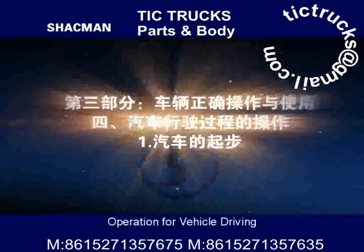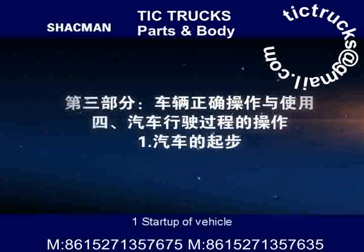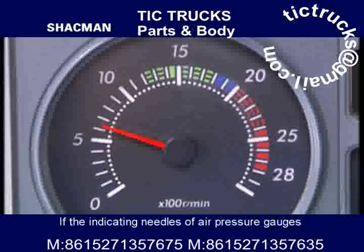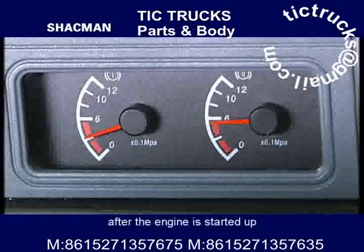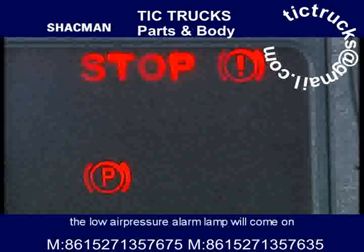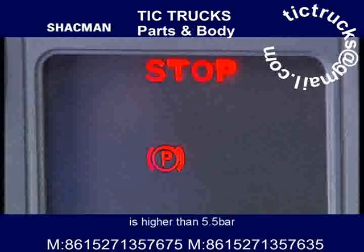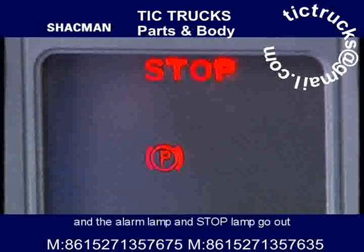4. Operation for vehicle driving. 1. Start up a vehicle. Starting conditions. If the indicating needles of air pressure gauges 1 and 2 are in the red zone after the engine is started up, then the pressure in the air pipeline is too low. The low air pressure alarm lamp will come on. The vehicle may be driven when pressure in the air reservoir is higher than 5.5 bar and the alarm lamp and stop lamp go out.